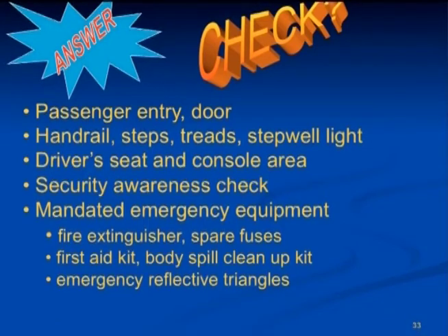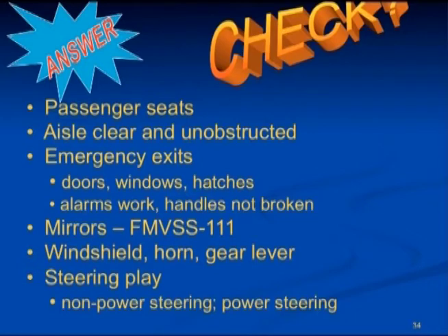Inspect the mandated emergency equipment for school buses. That includes the fire extinguisher, first aid kit, body fluid cleanup kit, emergency reflective triangles, and spare fuses if not equipped with circuit breakers. Continuing on with things that you would be checking inside the bus, check the passenger seats